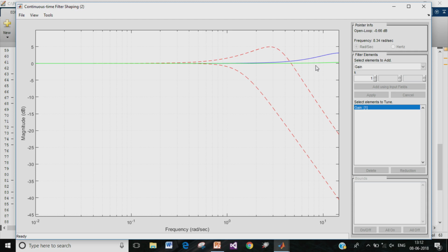That was because we chose a feedback controller whose gain had to be so high in order to meet the other performance specifications, such as rejection of output disturbance and input disturbance, that as far as robust tracking was concerned, the high gain resulted in very small variation in the transmission function of the overall system.